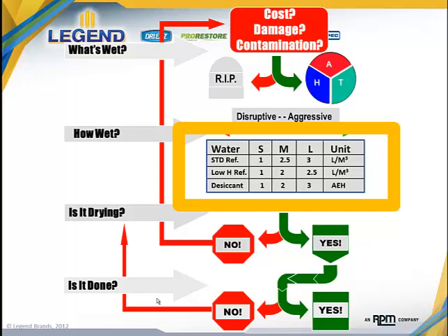First and most importantly, we have to understand the volume of air that we're attempting to dehumidify. The greater this volume of air, the more difficult it is to control the temperature and humidity within a space. Obviously, in other words, much larger buildings require more resources to control temperature and humidity than smaller structures and buildings. Secondarily, however, even if the volume of air is identical between two projects, that does not necessarily mean that the amount of dehumidification required is also the same.